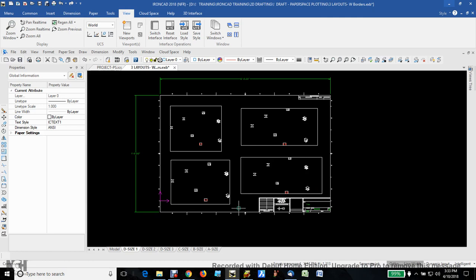So I can have as many views as I want, without causing too much confusion on a drawing, as many as you need. So now what I want to do is come up to this top left viewport. I want to double click inside the viewport, and you'll notice that the viewport gets highlighted a little bit brighter. So now I can pan around the model space and bring the view that I want in that viewport into play. Then I double click outside the viewport.